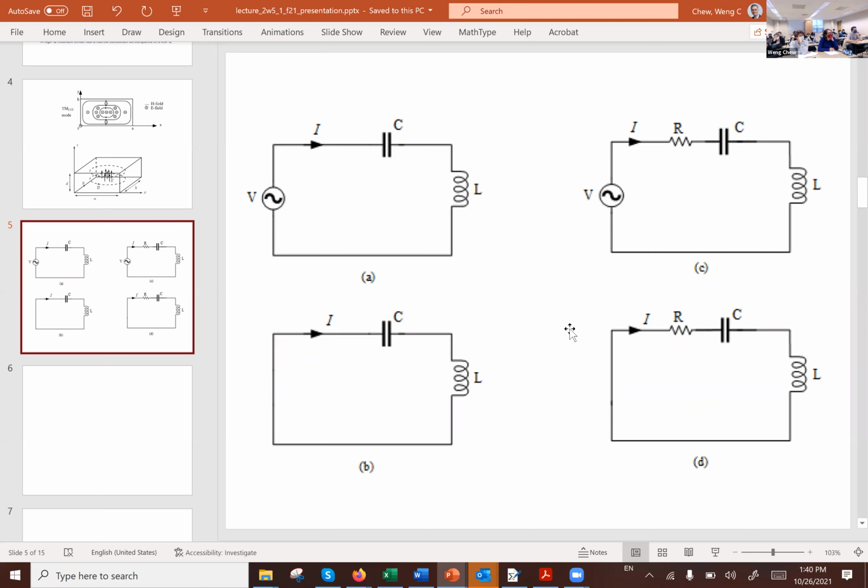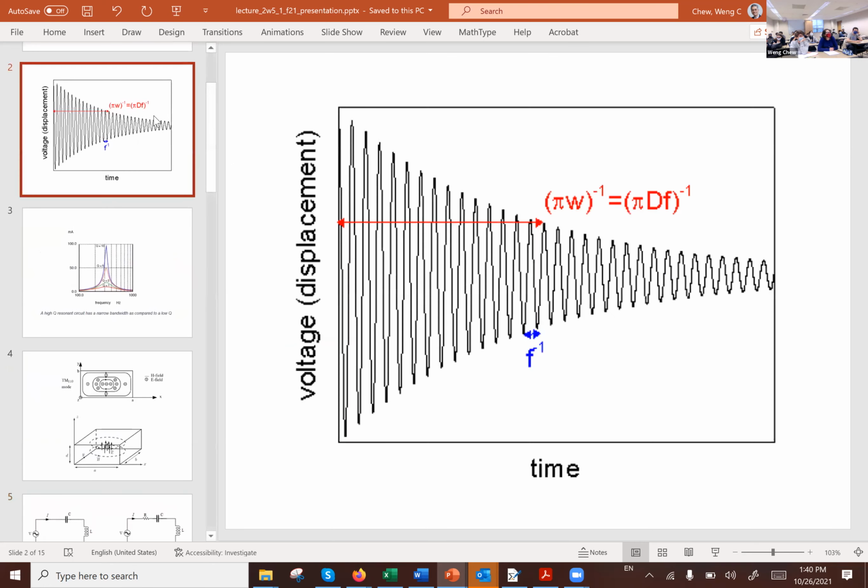Okay. However, if you were to set this problem up like the bottom right-hand corner with an initial value of currents and charges in the inductor and the capacitor, then the electric field and the magnetic energy stored would cross back and forth between the two elements, and because there's a resistor in between them, the energy gets dissipated, and the behavior of the current and the voltage will look like what you have in this picture over here.